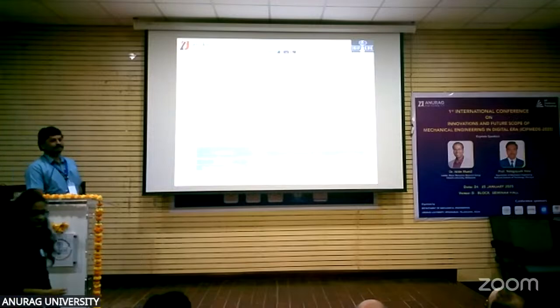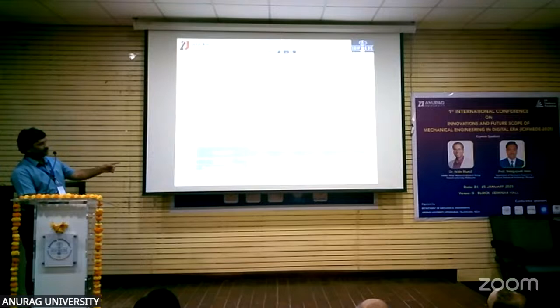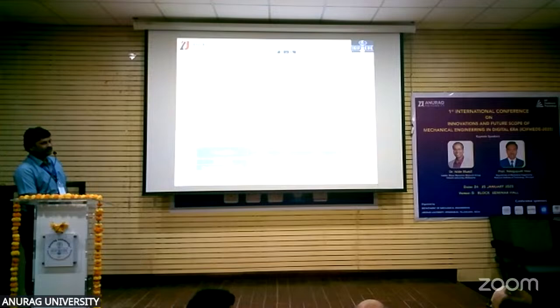The minimum value, the minimum strength. To get the minimum value, these are the parameters. The weld strength for the minimum is 17.5 Newton per mm square. This is by experiment, sir. We did the experiment and we also did the TLBO, and we compared the results.